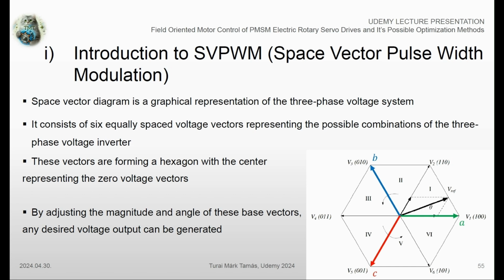So now we have a basic understanding that the angle of the resulting output voltage vector can be modulated with the help of the so-called base vectors that the inverter can directly output. Let's suppose that we would like to output a resulting voltage vector of 270 electrical degrees apart counterclockwise to the A-axis. This would mean that we shall operate in the electric sector number 5.